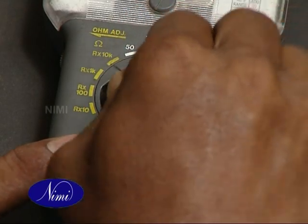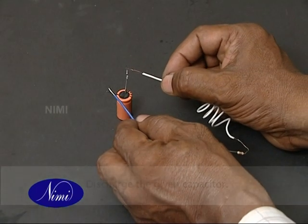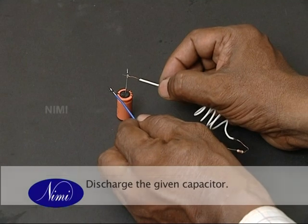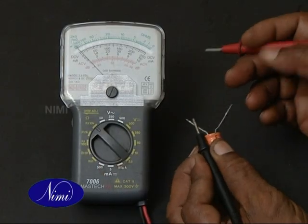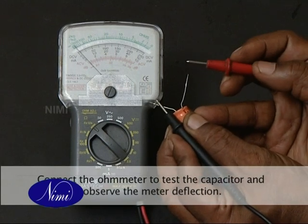Keep the ohmmeter selector switch at the higher range. Step 1: Discharge the given capacitor. Step 2: Connect the ohmmeter to test the capacitor and observe the meter deflection.